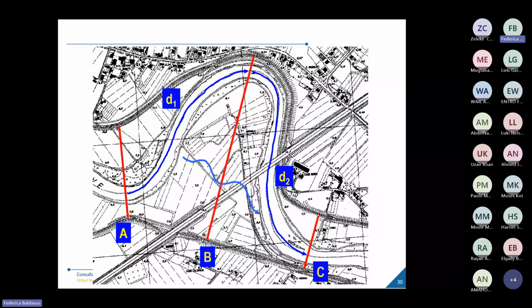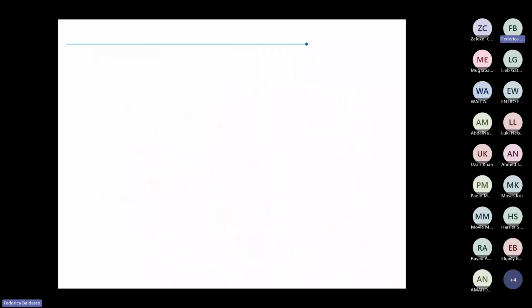Now keep in mind that, as I said before, the shape of the river actually has no influence for the model, because HEC-RAS software always considers the water to flow in a direction perpendicular to the cross section. So the schematization would be like this.